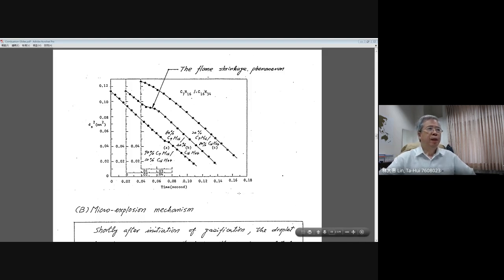Last time we talked about the miscible fuel. That means a fuel with at least two components, and those different fuels can mix well together without any additional chemical. And I tell you, there is a very important inference coming from the Lewis number of liquids, since for liquid the Lewis number is always very big. That means the thermal diffusivity is much stronger than the mass diffusivity.